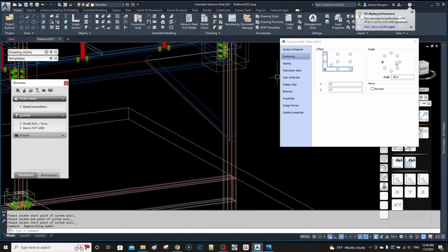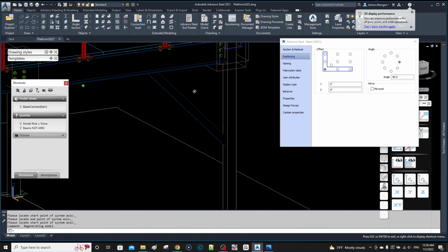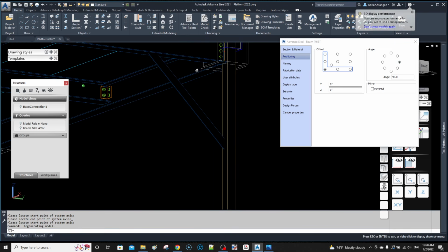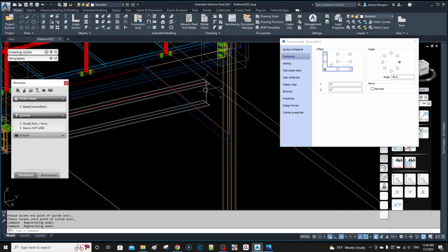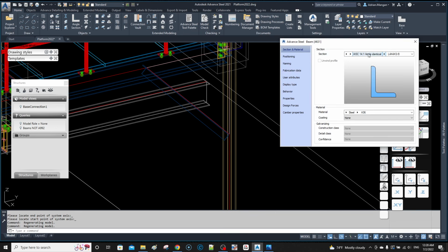That's not the way we want it. I think if I go all the way here, sometimes it's a bit of guesswork. We'll just put one brace on the inside, okay? Now the problem with this is we want to put it sometimes on the gauge line, sometimes on the center line. So generally with braces, I will put them on the center line. It's a 4-inch angle, so we can put it on the center line.